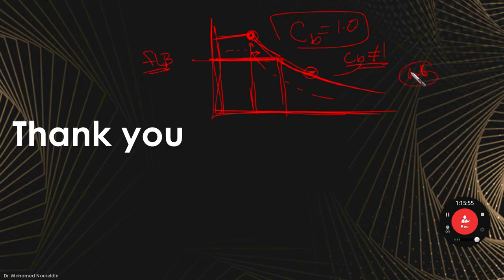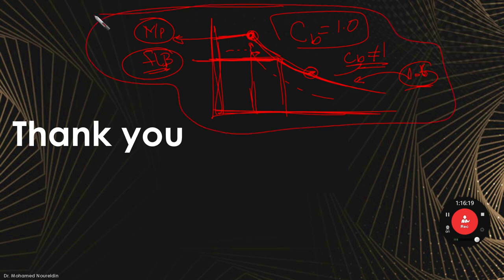Then we need to multiply whatever we obtain from the curve by 1.6. But remember well that this value need not exceed the plastic limit, which is Mp in our case, okay? Or the flange local buckling, for example, if we are talking about a non-compact section. So this summarizes what we have done for today.